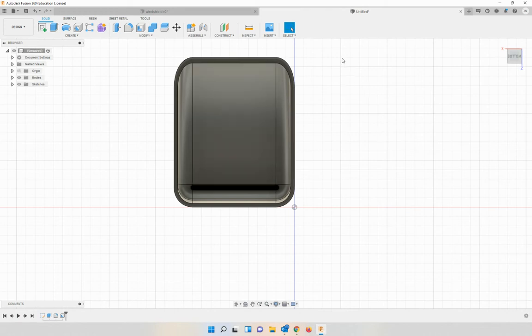And what I'm going to do is create a sketch on this surface, the bottom of the windshield. And I'm going to draw a diagonal from this point to this point, which will allow me to find the center point of that rectangle and draw a center rectangle that is 48 millimeters wide and 38 millimeters tall. So let's go create sketch.